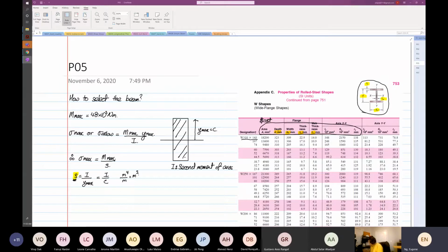That's the web. Then you have IXX, second moment in the X direction. You also have IYY, second moment in the Y direction. So for your term test, we're only going to focus on the XX direction. I'm not going to do the YY direction with you because I haven't taught you yet. Now, can you all see this? S as a function of small x. So this S in the subscript of X corresponds to this S over here. So now we know our M max.